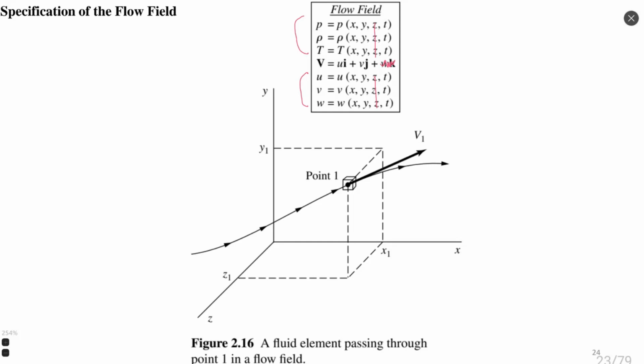There is also another simplification that we might adopt. It is very useful when we see stationary flow, when there is no time. I will cancel time from here, and we see stationary flow which does not change in time. It requires only 2 parameters in case of two-dimensional flow, and simplifies the flow model significantly. Almost all analytical models which you can find in the book of Anderson are solutions in case of stationary two-dimensional flow. So when possible, we will try to go from transient with time to stationary without time, and from three-dimensional with Z coordinate to two-dimensional without Z coordinate. In such case, I also forgot to cancel the W component of the velocity in two-dimensional case.